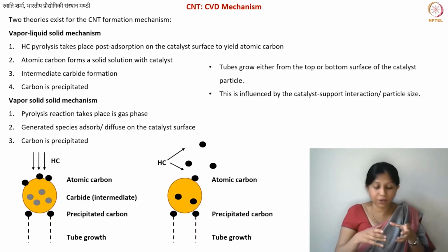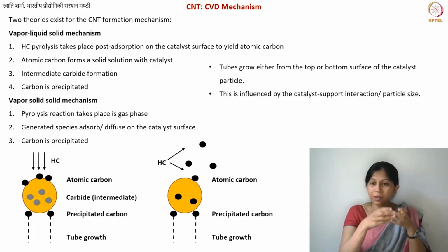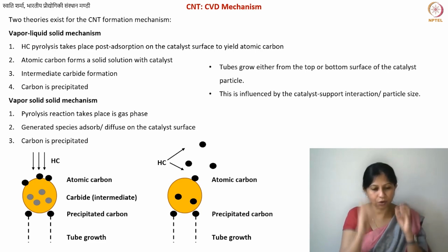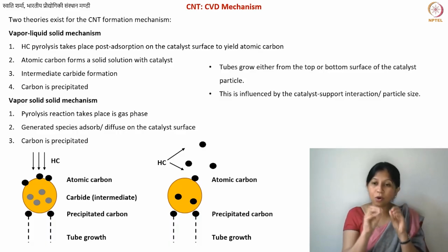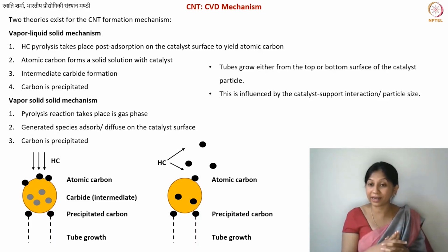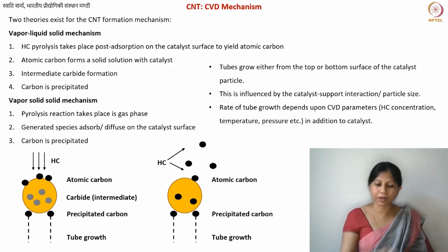Basically, during the deposition of carbon, when the tube was growing, did you have enough lift force to lift your particle up or not? Either way, the carbon does get deposited and the carbon tube does grow, which also confirms that the carbon particles do go inside your catalyst. And that is why they can come out of any surface of the catalyst, whatever is more convenient at that given point. So, okay, that is something which we understand about carbon nanotube growth.